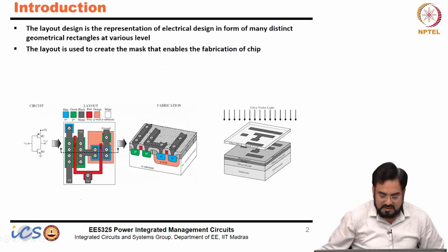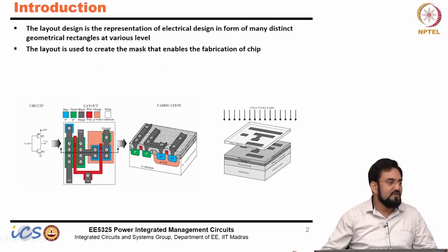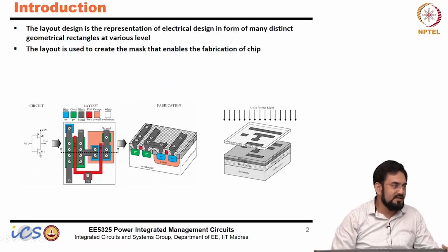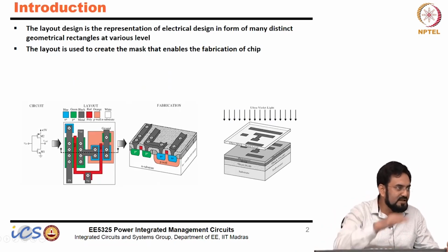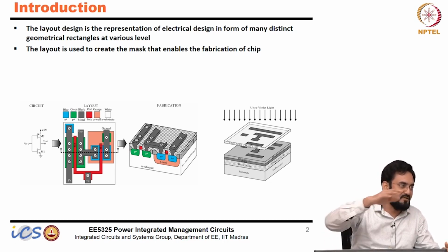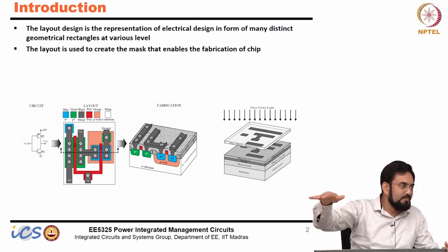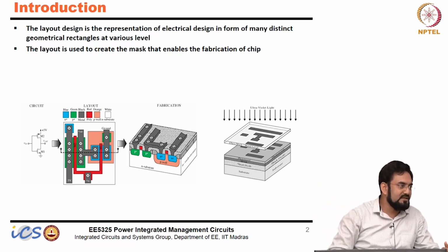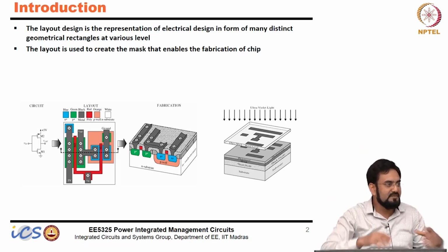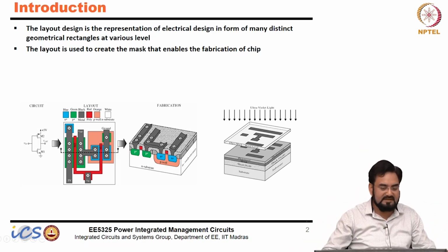That's it. Okay. So if you go to how any device gets fabricated, you have a substrate, and on that you grow different layers. You grow your diffusion for well, then you grow your source and drain, poly, gate oxide, everything, layer by layer, and when you complete everything, it will give you this structure.